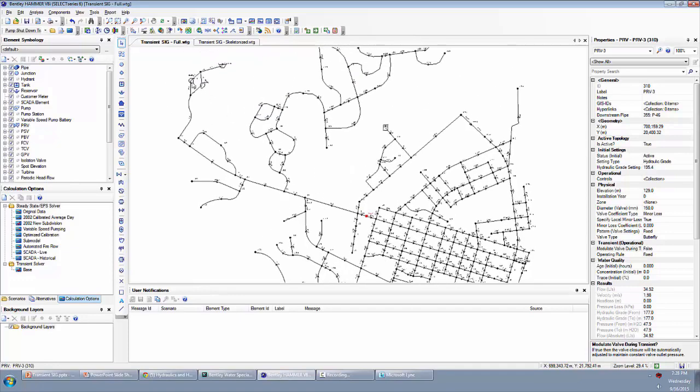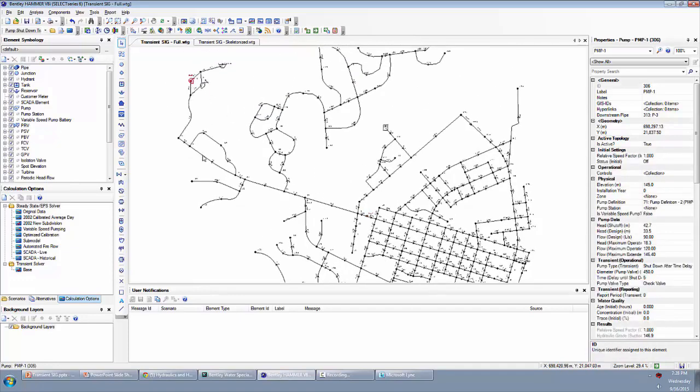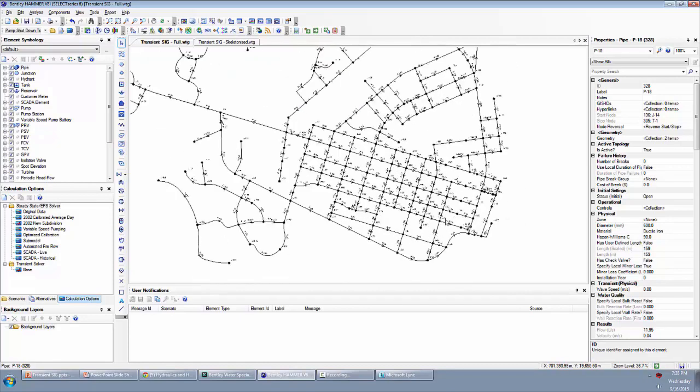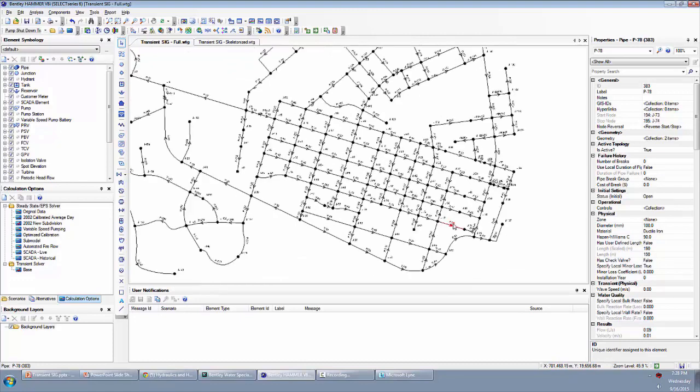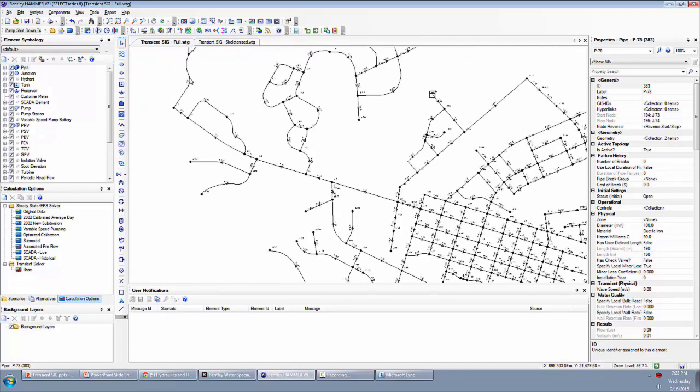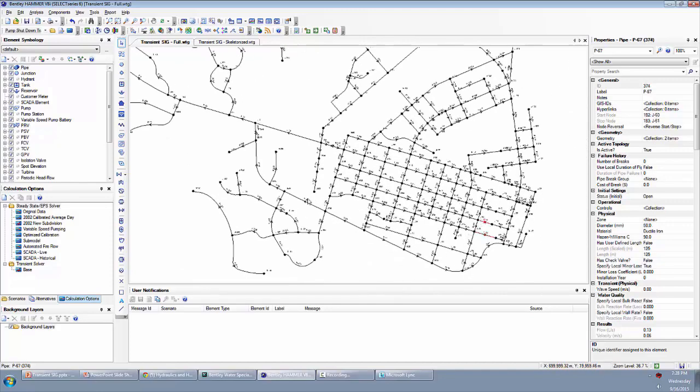Because, for example, in this case, you've got a pump station. This is basically your main line out here to the tank, what we have in the skeletonized version. And that's really going to experience the worst transients as a result of a pump shutdown. And when you get way out into the model way over here, the transient waves tend to dampen out, especially when things are looped around, and just the friction tends to dampen things out. So usually, it's not going to be a problem way out in the system. So by focusing on the skeletonized version, you can be pretty confident that if you can mitigate harmful surges in the skeletonized version, then the rest of the model that you didn't include should be okay.